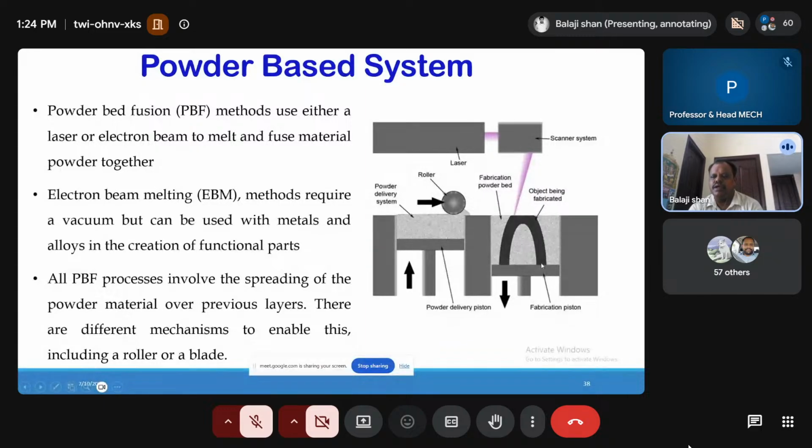After a 50 to 60 mm gap, later we record the 20 to 30 mm melting area. So, based on that area only, the laser power source should be directed. The remaining area, the laser power should not be passed through the powder. Where the laser power is passed, that particular area of metal should be melted and cured on the powder bed.